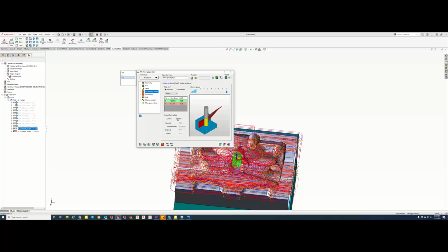smaller end mill. And that's right when the big recession hit, where any dime that we could save, we needed to save money. So instead of paying for, let's say, a $100 1/2-inch end mill, we were able to utilize a $25 1/4-inch end mill and still get the same performance as if we were running a 1/2-inch end mill with traditional machining. So great point, Greg, because when we're getting into those Swiss or the mill turn machines, size is always an issue, there's just not enough room in there, because we're trying to compact so many tools and tool holders and collets and all that stuff into a small space. So now you guys can utilize those smaller tools in there, but still get much better results, as well as with our live tooling. And even on the milling side.